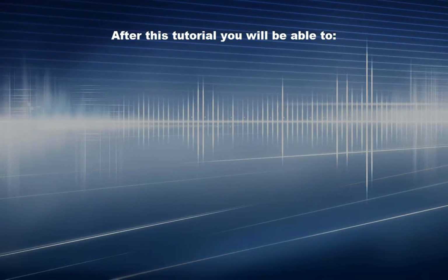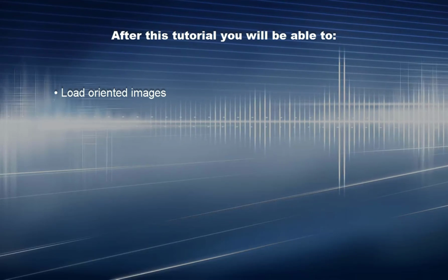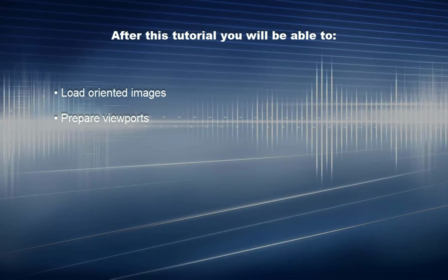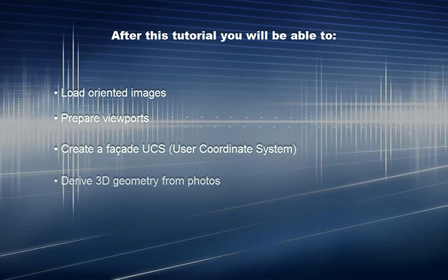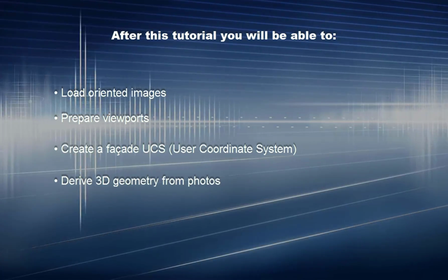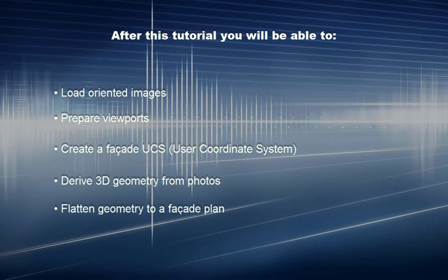In this tutorial, you learned how to load oriented images, prepare viewports, create a facade UCS, User Coordinate System, derive 3D geometry from photos, and flatten geometry to a facade plan.